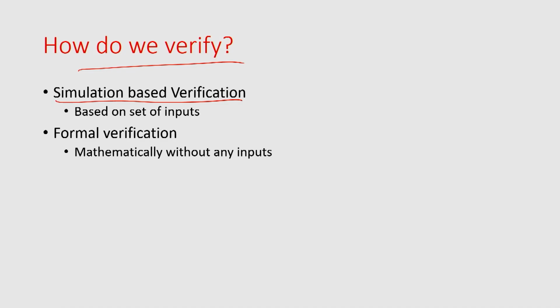You think about you are doing some operation where there are two inputs of 32 bits. So effectively you have 64 bits of input and the number of possible values is 2 to the power 64, right? Ideally, for checking the correctness of your system, you should run all 2 to the power 64 possible cases, right? Think about the floating point bug that I talked about. To verify that, you ideally have to give all possible combinations of input and check the division, right? Then only you can identify such a bug.